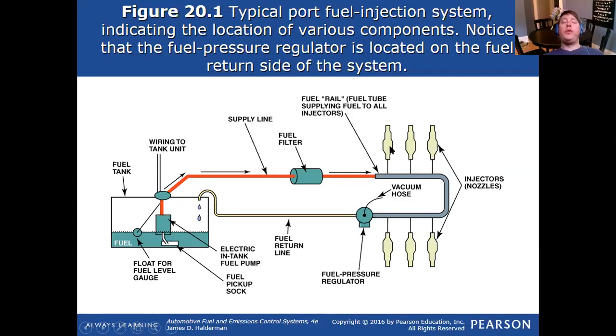I wanted to talk about that because there are some situations where the fuel systems aren't going to look anything like what's even in the textbook if you get one of those one-off old school vehicles. And those mechanical style fuel pumps on older vehicles can be replaced with electric inline pumps. So keep that in mind if you have an older vehicle and you want to put a more reliable fuel pump on it.